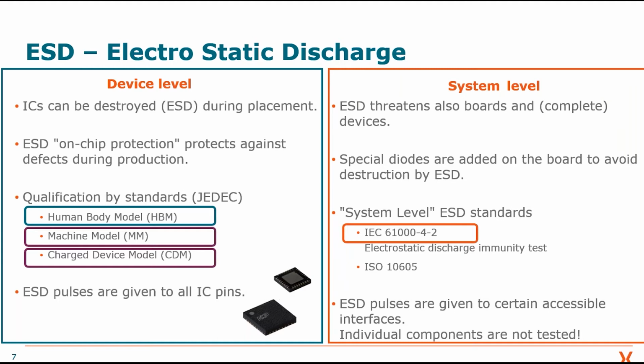Thank you, Lukas. So, as Lukas said, we have ESD, and ESD is happening everywhere in our daily life. For us, for hardware engineers, we have to consider ESD especially in production and in the ordinary usage of the device. And therefore, there are two levels of ESD. One is the device level and one is the system level. And we want to talk about both today.